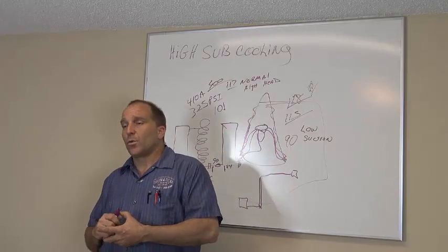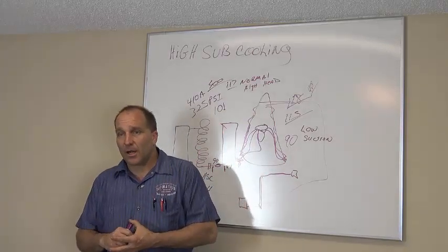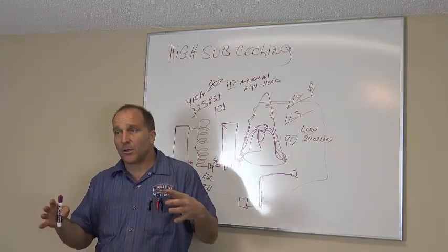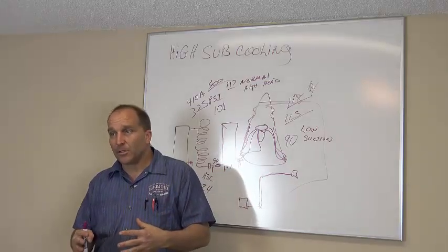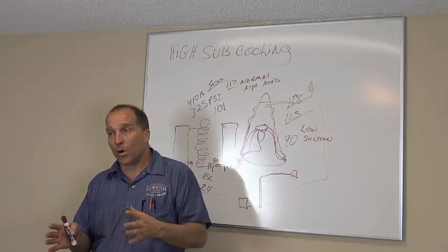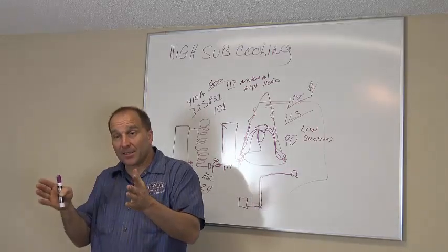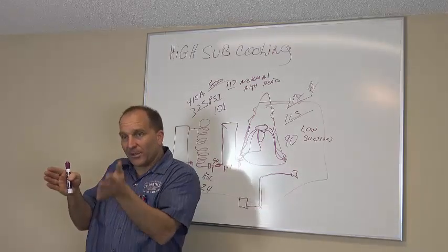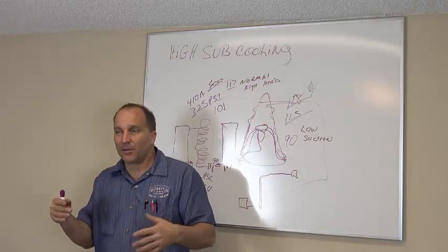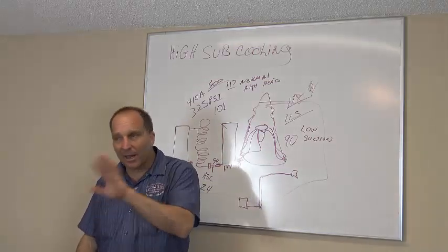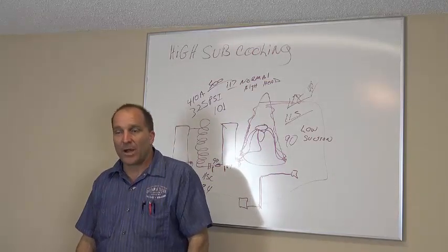You've got to make sure that when you go to every job, these condensers are cleaned properly. Okay? So you got to look to make sure that the condenser coils don't have a double coil. The old Lennox systems, when you look at the top of the coil and the inside, it's a double coil. And nobody ever cleans it. I'm telling you, nobody ever cleans that coil. It's an old